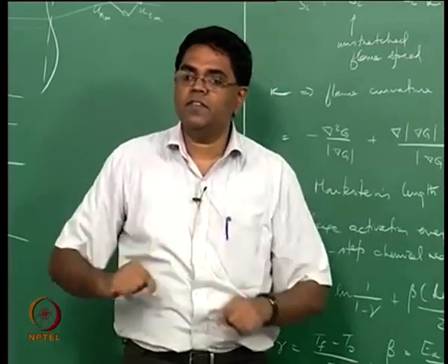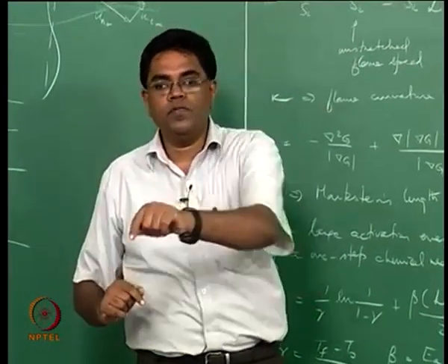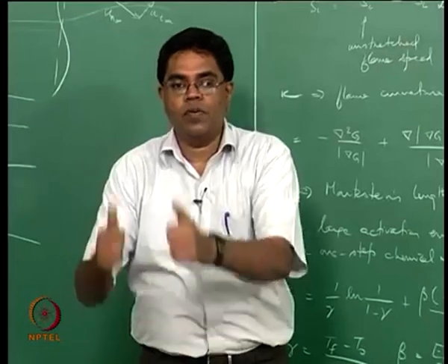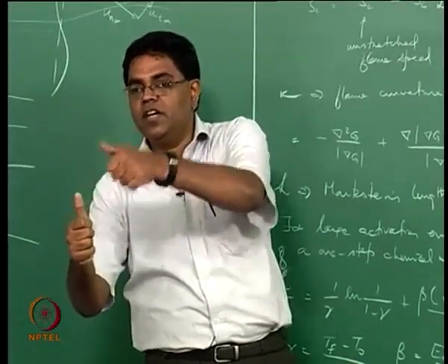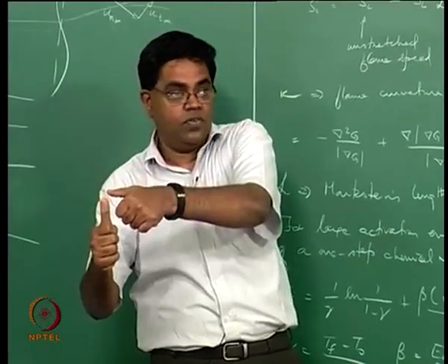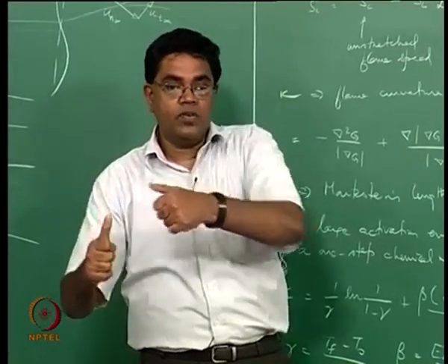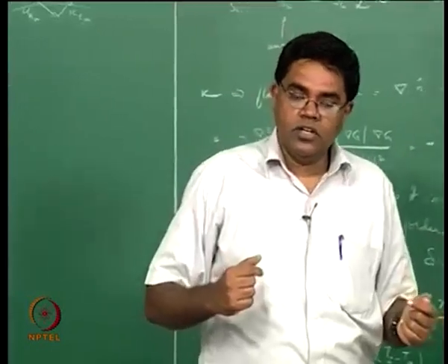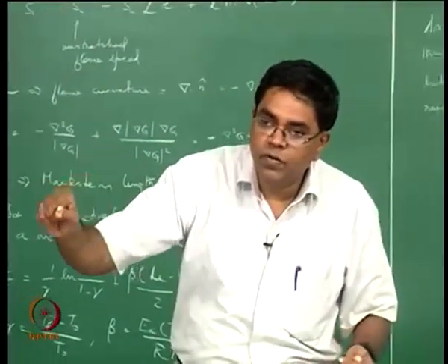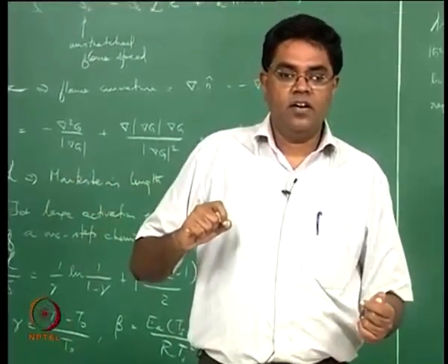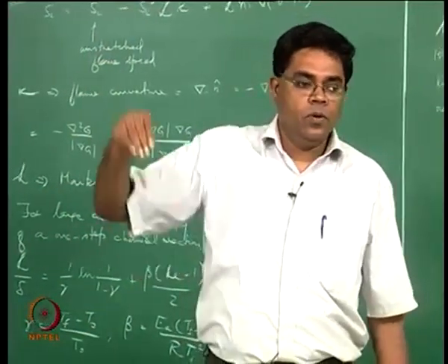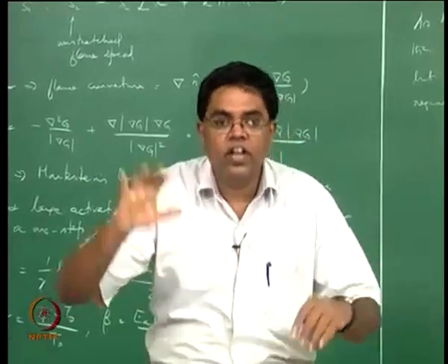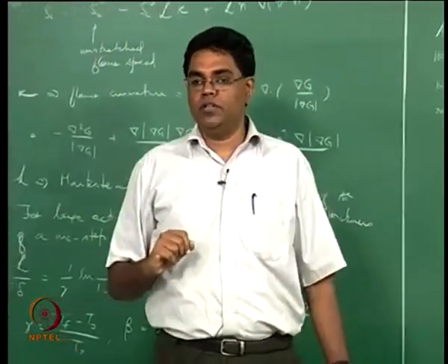But that was not the case for the flow as well. The flow wasn't uniform there. It is coming out of a burner and it has to satisfy the no slip boundary condition. That means the flow velocity has to start from 0. So we tend to begin to think, wait a minute, if you are going to have a 0 flow velocity there, that means the flame should be able to propagate against the flow right there along the walls and never really be stabilized above the burner.